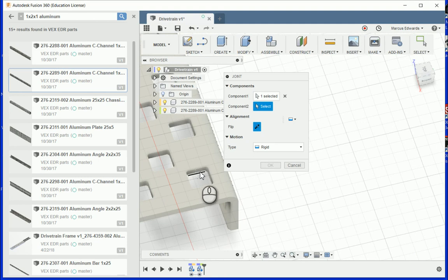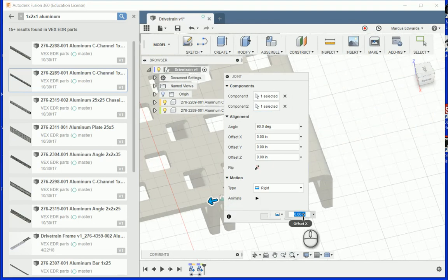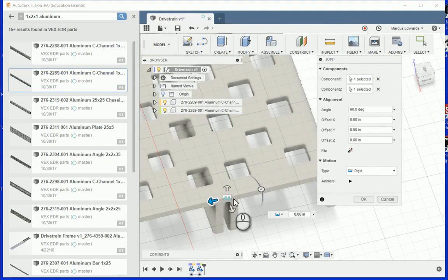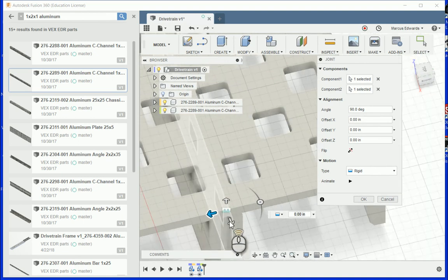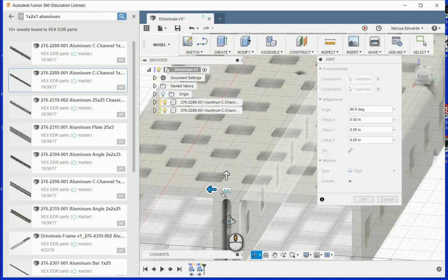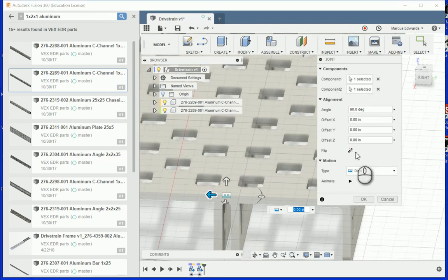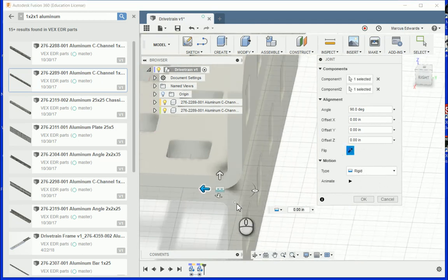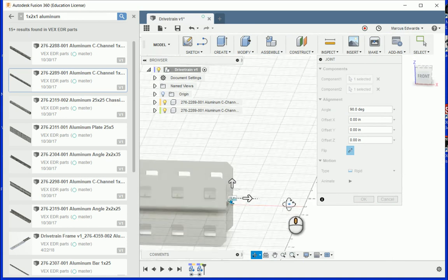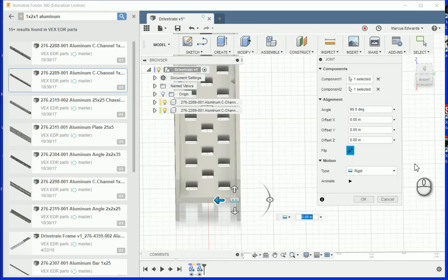And one thing that you can do when you're on a plane, if you go ahead and hit Control, it will lock those in. Then you can select the second one. So you'll notice right then that it brought those two points together. Okay. Now, can I move those? Yes. Can I flip them? Yes. So as I flipped it up, you're going to notice that it perfectly aligned those two and it created a joint.